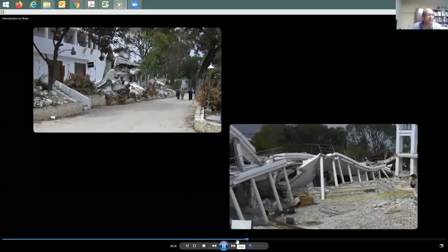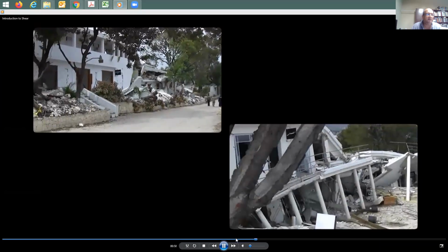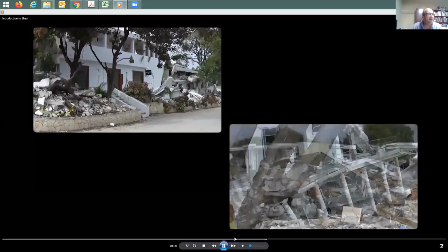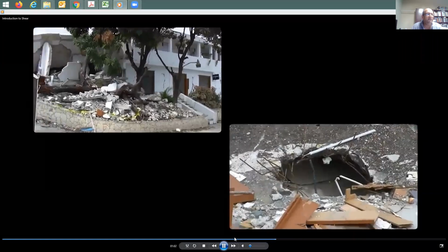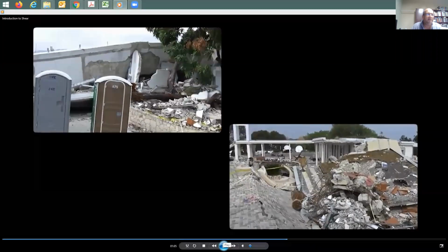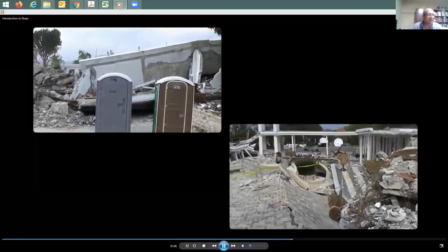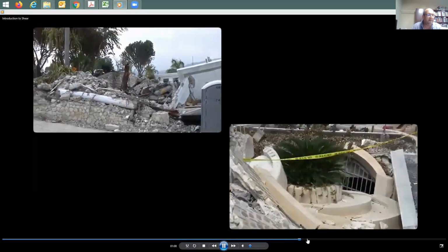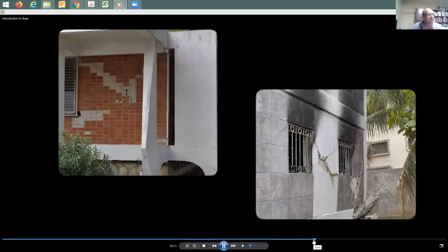Some shear failure examples, so that you know that shear failure is terrible. It's just bad. This is not flexure failure. Of course, any failure is bad, but at least in flexure failure, you see the beam deflecting and coming down. So it's going to give you lots of warning. In shear, you're not going to see lots of warning, and you're going to see that now in testing.